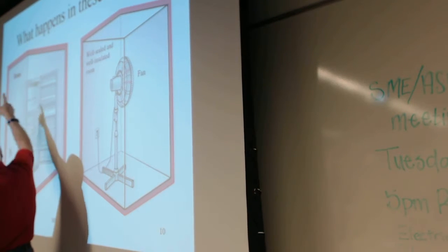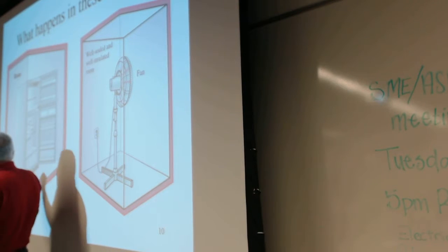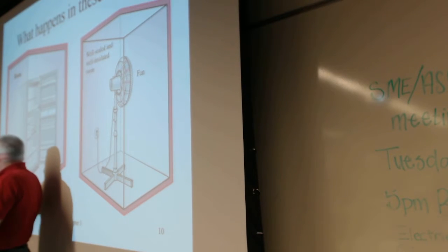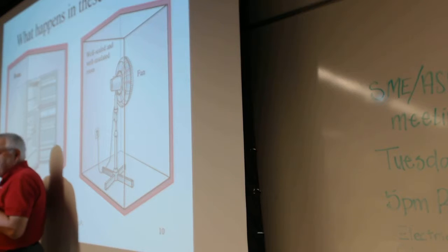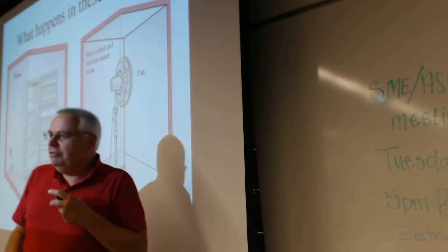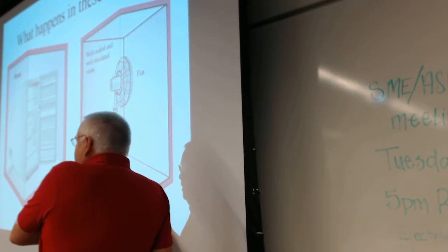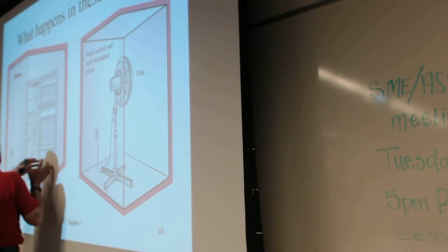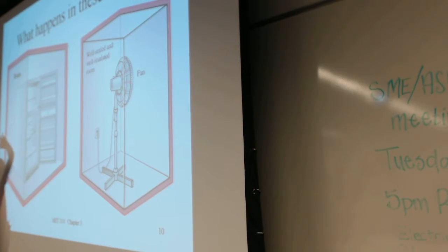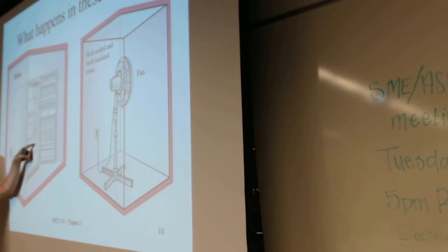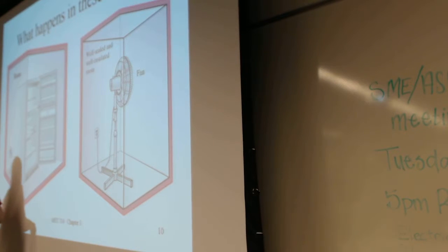this room is completely sealed. It's insulated. There's no heat getting out. There's no heat getting in. But there's a plug here. So what do we know if we've got a 100 watt power consumption? Are we generating 100 watts worth of heat energy? It's taking like 300 watts of cooling from the inside of the refrigerator and taking it to the back, and out comes 400 watts worth of heat. So right in front of the refrigerator it'll be cool, and everywhere else the room's going to get hotter.